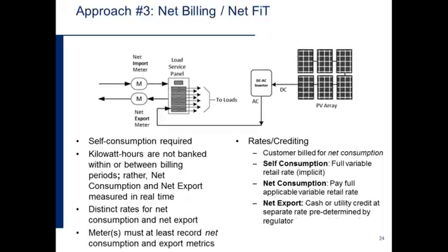So finally, one emerging solution in many jurisdictions that perhaps used to have net metering is a shift to this concept called net billing. And many would refer to this also as a net feed-in tariff. Here the customer has 2 meters. The system is wired to give the customer the opportunity to consume their own electricity first before that power gets pushed out to the grid.